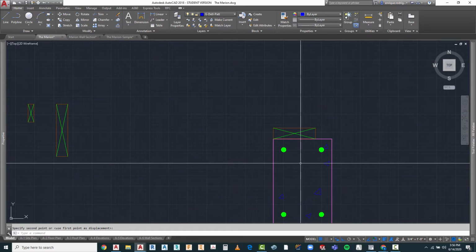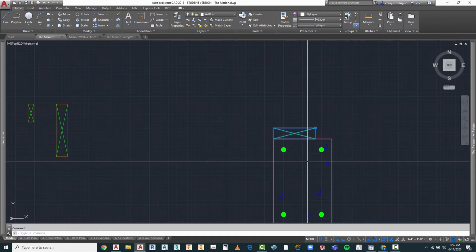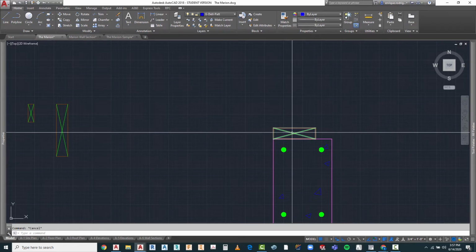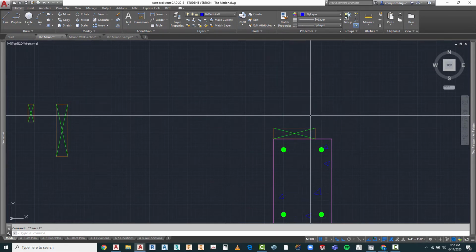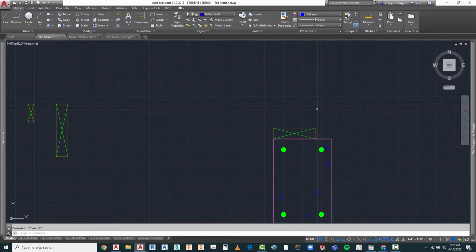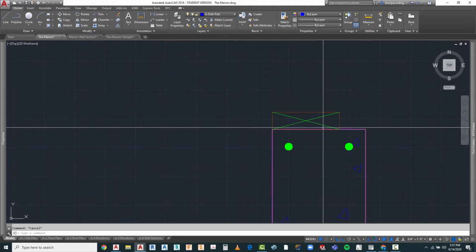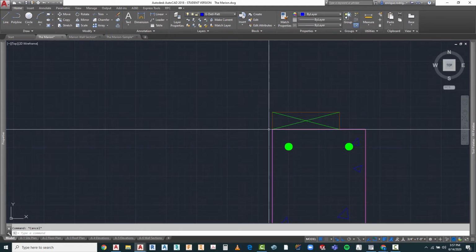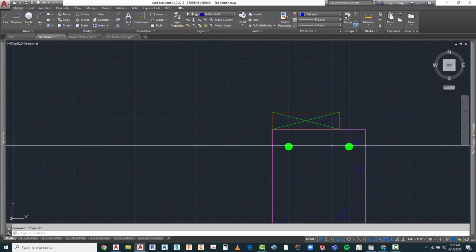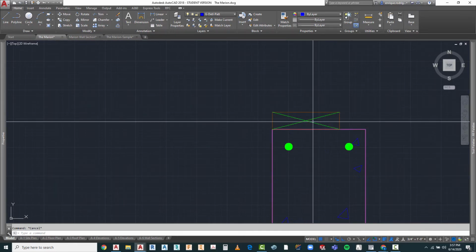They need to be at the beginning and end of any singular pieces of wood that are on there. Again, for uplift capacity because of hurricane force winds, they will also be located certain distances apart, whether it's 2 feet, 4 feet, 30 inches, etc. Oftentimes they will also put a piece of insulation membrane underneath the wood to seal for any discrepancies between the wood and the concrete.